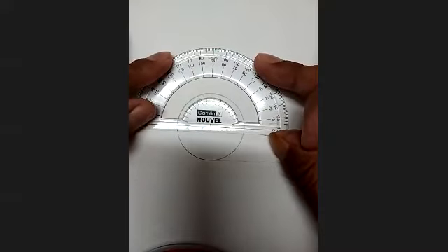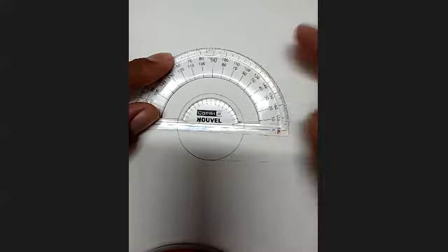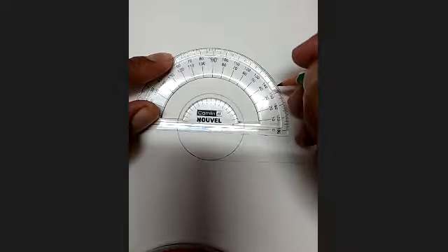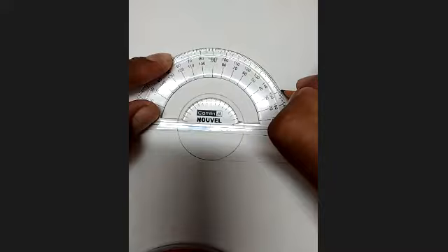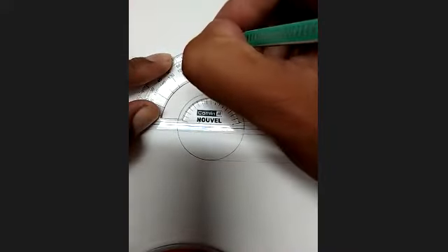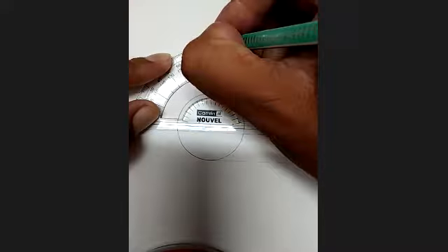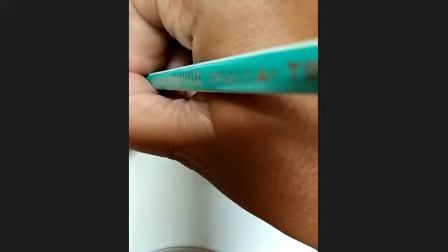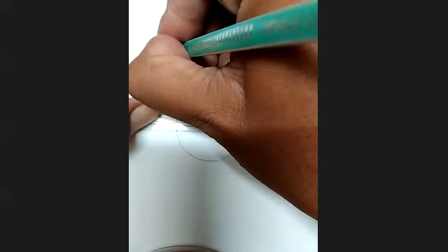Now you will learn how to divide the circle into a number of parts. If you are trying to divide this circle into 12 parts, then 360 divided by 12, how much are you going to get in degrees? Yes, 30. So 30, then 60. I will take this, so we will get the exact point. Then again, one more point at 60, and then 30, right? So I got these points here.